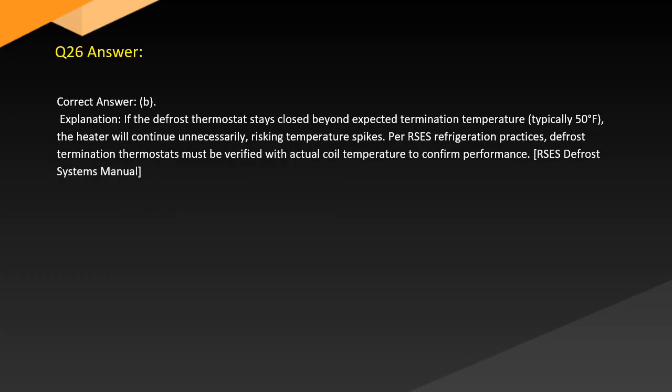Answer. Correct answer: B. Explanation. If the defrost thermostat stays closed beyond the expected termination temperature, typically 50°, the heater will continue unnecessarily, risking temperature spikes. Per RSES refrigeration practices, defrost termination thermostats must be verified with actual coil temperature to confirm performance. RSES Defrost Systems Manual.